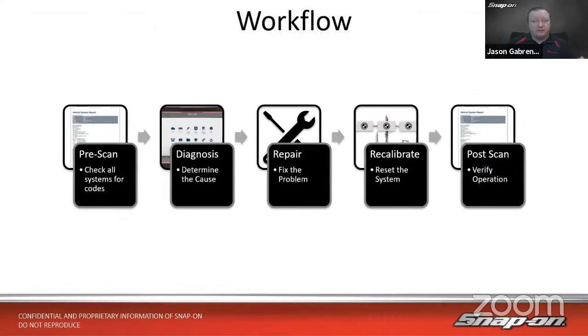So what we want to do is, when we're working on a vehicle, pretty much just about anything we want to do on a vehicle, but especially when it comes to diagnosis, we want to have a clear, repeatable workflow. So that way it works like a checklist, right? So I can make sure I don't miss anything or miss any steps along the way, which could lead to a misdiagnosis. So we want to walk through the complete process all the way.